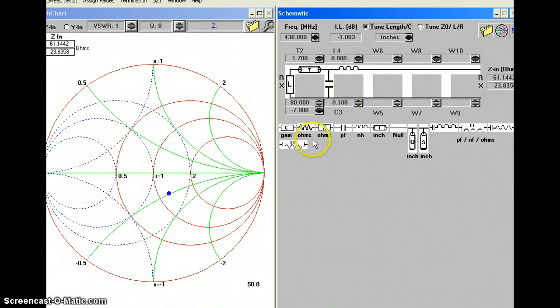To review our circuit, here's our antenna right here presenting some impedance. It is offset by a feed line that is 1.7 inches. Now we're going to add some circuit elements in here to get this to 50 ohms. How do we do that? What's nice about this little program is that we can come in here and play with these numbers. Our goal is to move this dot into the center. Here's why I just love this program: we could solve and write an equation, a function, to do this. It is very complicated, but this makes it really easy once we get the model set up.